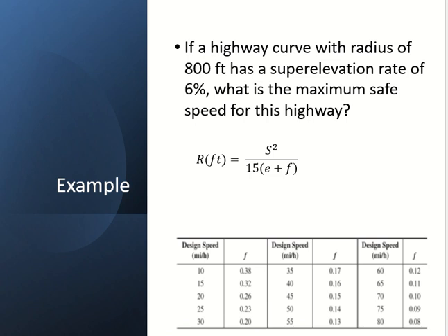In this case, speed and F both are unknowns. Either we produce another equation, which obviously we cannot do, or we assume. We do trial and error with the assumption. So we have to assume some value of F here, and then we will see what our answer is. Then we check the answer. So which value do you want to assume?